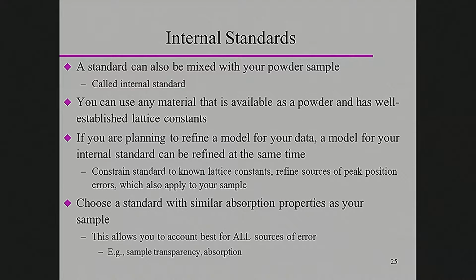Another big opportunity in powder diffraction is to use an internal standard. Okay? Because again, a powder can be more than one phase. So why not mix a standard in it? That's what we call an internal standard. You can pretty much use any material that is available as a powder that has well-established lattice constants. Of course, using a certified standard has the advantage that you're really sure about the lattice constant.